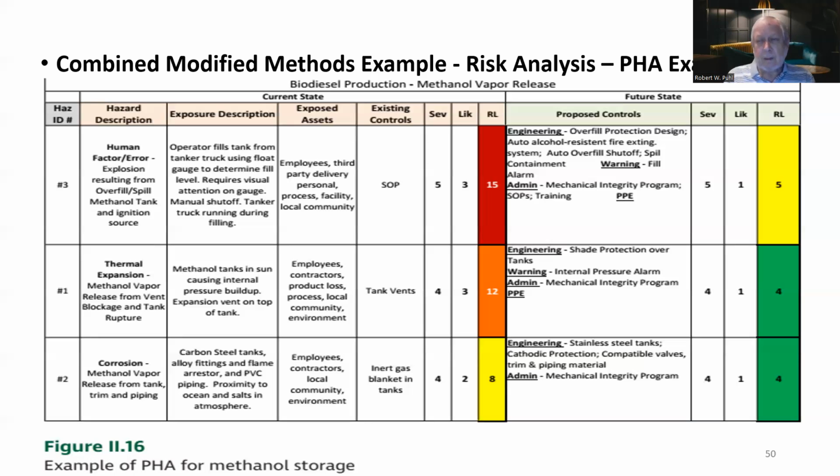Make sure it works, and that the vent blows or goes off at or below the MAWP, the maximum allowed working pressure. So if you have a tank that has a MAWP of 350 psi, that vent better be designed to go off at 350 psi or less.